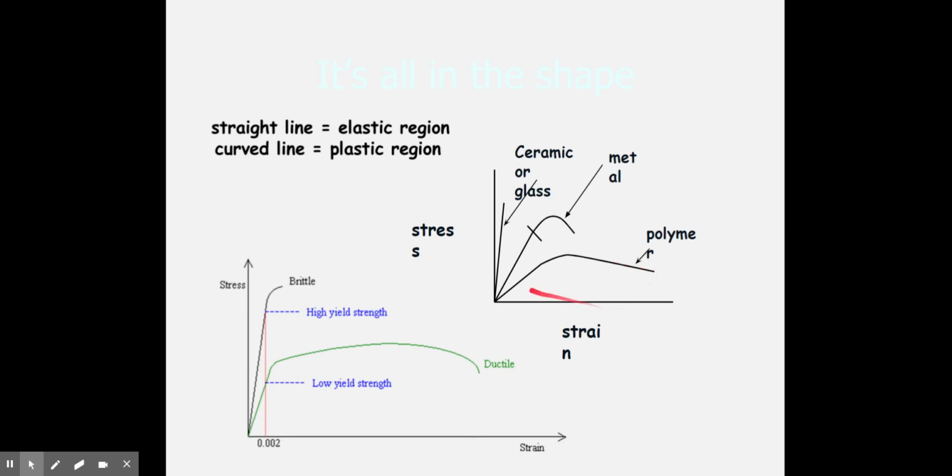So the amount of strain it can take, which is the deformation of it, is what's going to keep this line going farther and farther. But you'll notice it didn't get up as high. The stress comes up here, and then it starts to deform, whereas this one doesn't start to deform until here, and this one doesn't start to deform, but then fails right away once it does, at a pretty high stress.